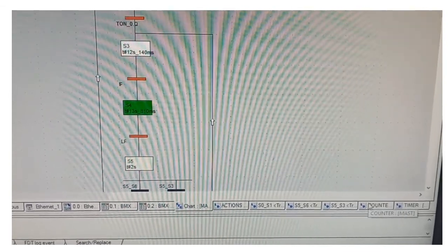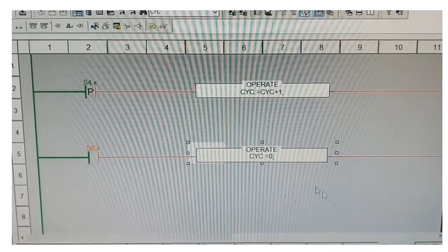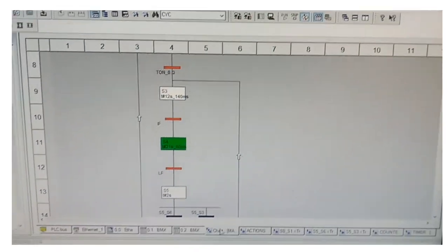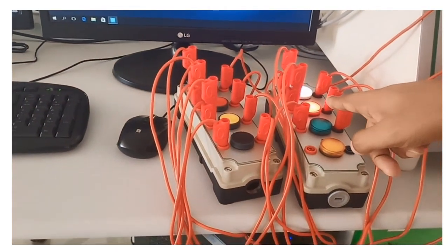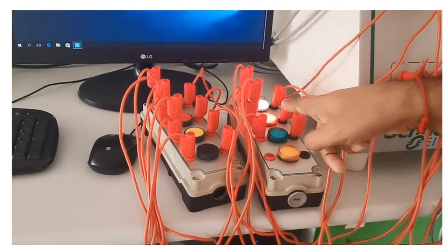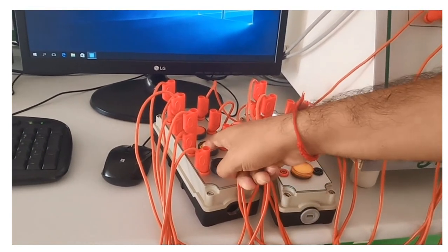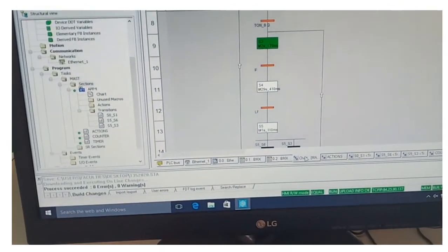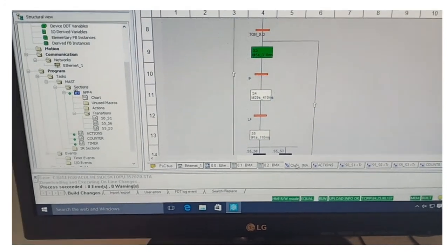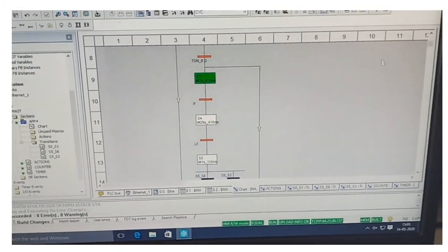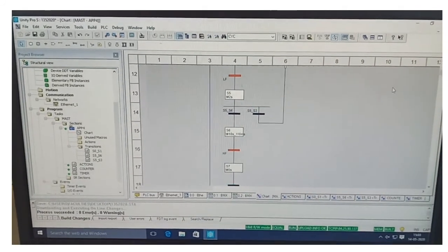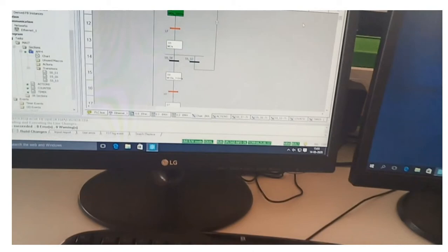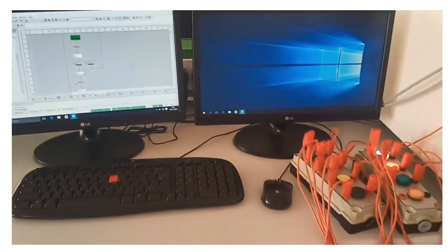Now, once again it will go for the low position switch after this, because the cycle is not completed, right? So it will come to the low position. Because the cylinder is in the intermediate position, I will check the low position. Now 1 minute drilling is done. So twice the drilling is done. Now once again it will go up and it will reach the intermediate position. In the intermediate position the cylinder will start to extend. So it will extend up to the low position.